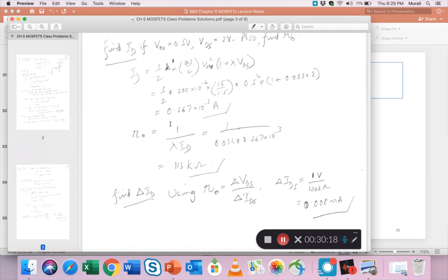This RO is the output resistance. This is different from the triode region resistance that we talked about earlier in this recording. That's a whole different animal, so don't get confused. This is strictly to help us model the output resistance when channel length modulation is in play.